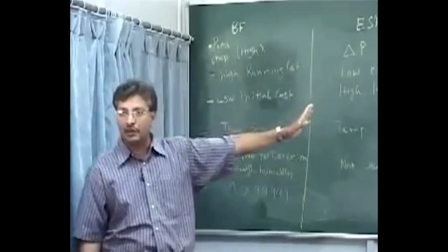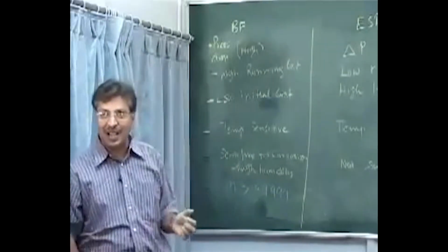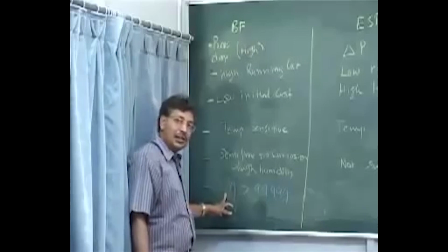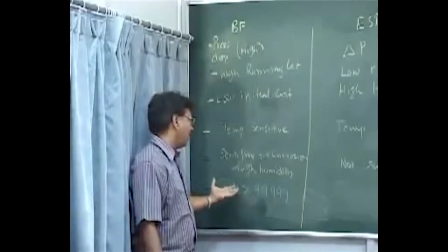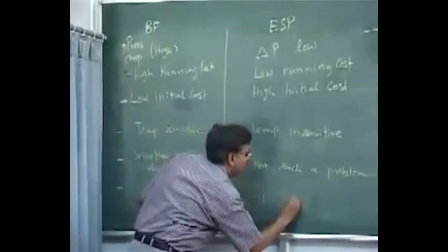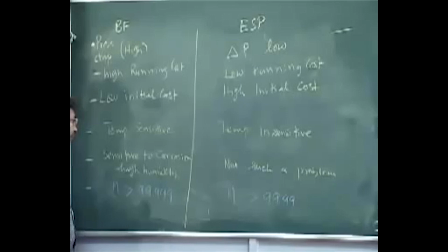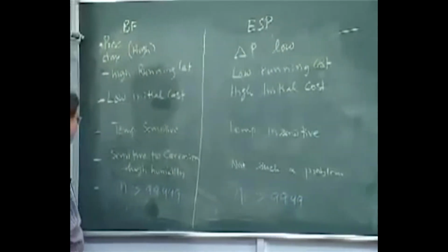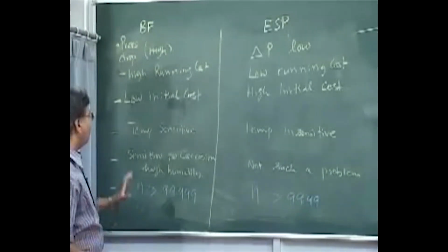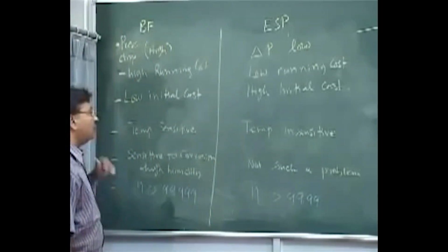These costs are insignificant for me, because if a little gold escapes, then I don't want that. I am just giving you a very coarse example. For example, in the cement industry, because cement is a product, they will have this, because the efficiency of the bag filter is high. Efficiency here is also high, of the order of about 99%. They are both comparable, but depending on what situation you are in, you have to use one or the other.